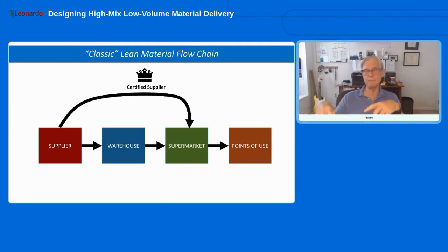Second is we're creating challenges for the operators because number one, they've got to find the parts they need if they've got too much in front of them. And potentially, if space is an issue, they have to walk. You're asking them to have to walk to retrieve their parts. So our basic philosophy in the world of lean is to reduce the amount of material you have at the station to something that's manageable or maybe minimal right at the workstation.